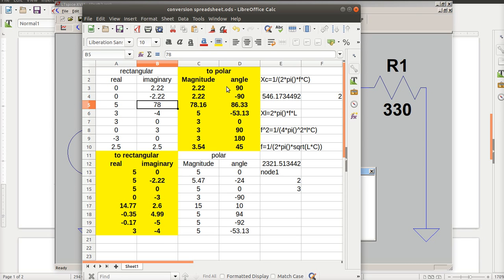And at the same time, the voltage level can be quite high. So if I lower my resistance, I will get even a bigger swing. So I can actually probably get 7 or 8 volts if I choose the right resistance from an analysis standpoint. I probably can't build it because I've got to have something to limit the current. But what you see is my voltage is in fact going up there at that point. And we probably can actually get it above 5.